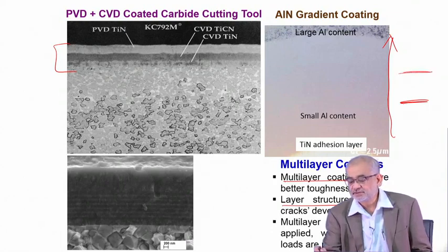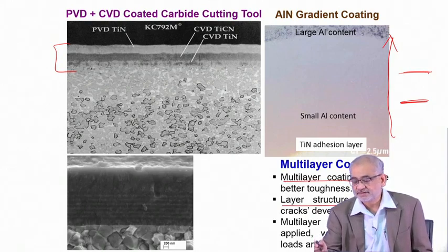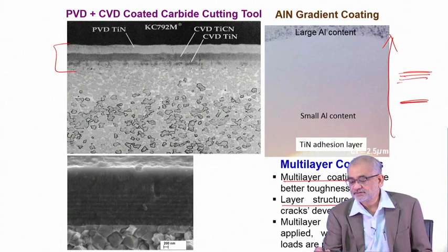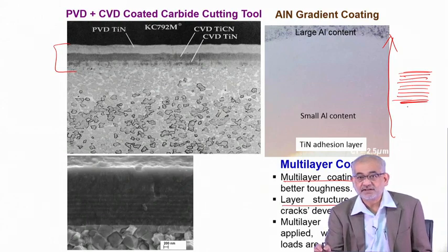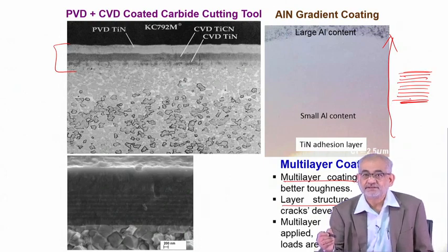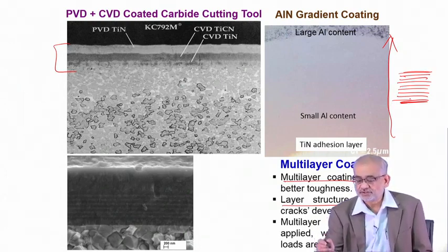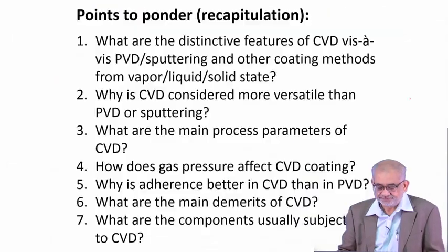But if the same coating, maybe a carbonitride or a mixed nitride or a silicide, is done in alternate thin layers, very thin alternate layers, then the mismatch is actually accommodated nicely, and the stress generated at the interfaces is minimized, and as a result you can make a much more adherent, durable, and mechanically stronger coating on top of the substrate.